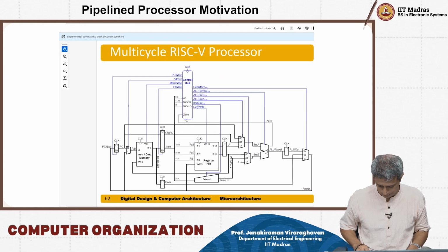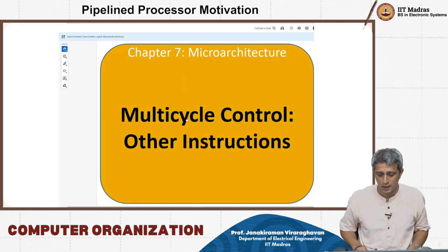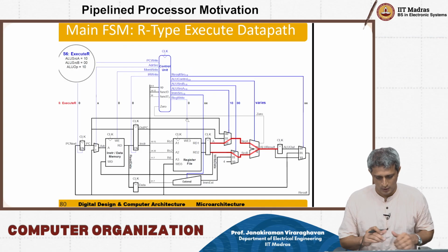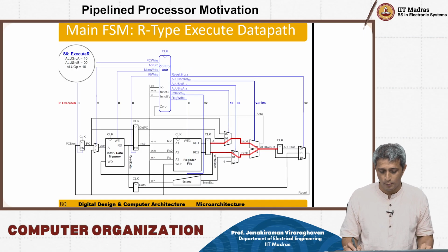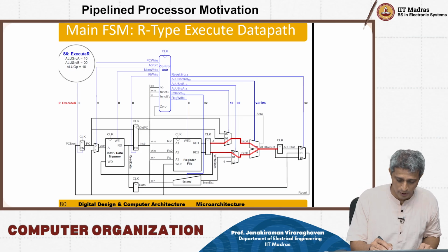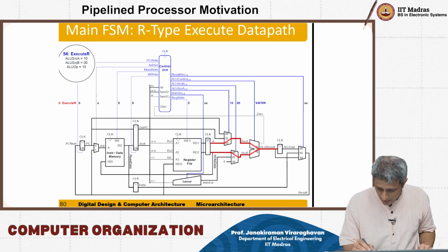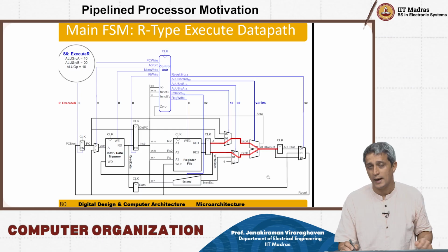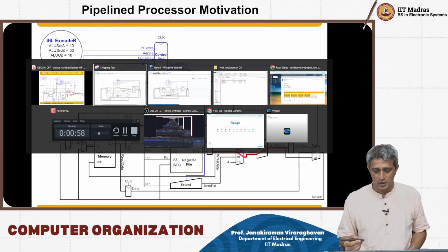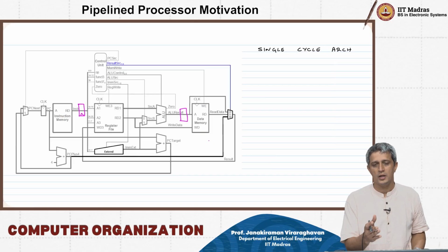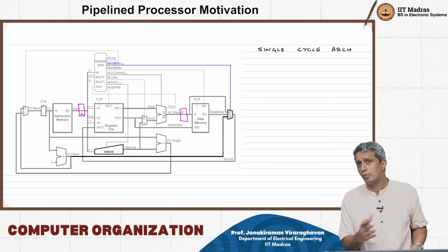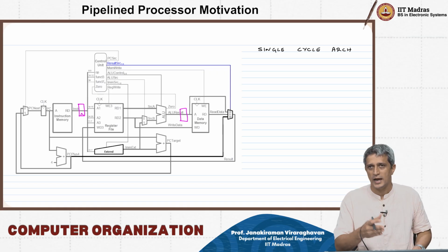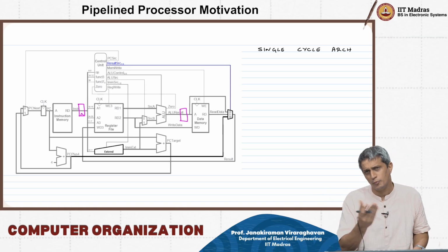Let me show you this diagram here, and it will become very evident. We have put in a flip-flop right after the instruction memory output, then another flip-flop after the register file and another after the ALU result. But what I have drawn here is that I have removed the flip-flop after the register file. So I could technically combine those combinational blocks of register file, decoder, extender and all that, put them along with the ALU, and then put a flip-flop after that.